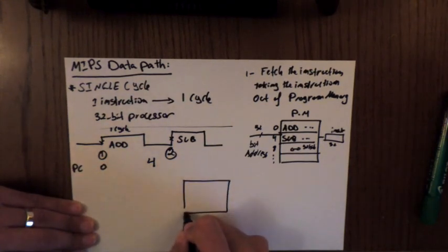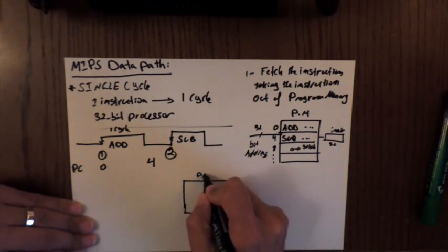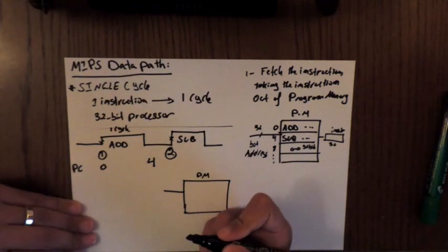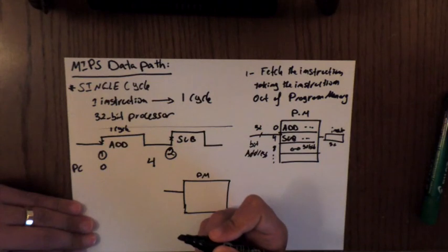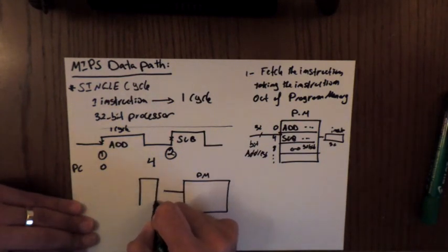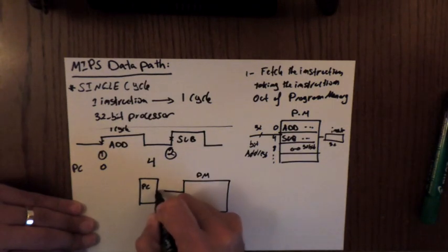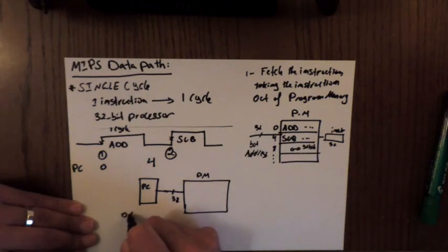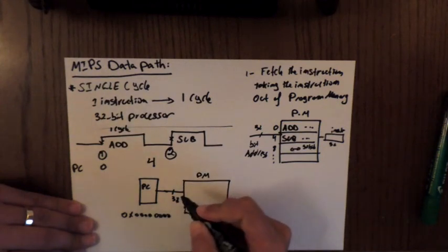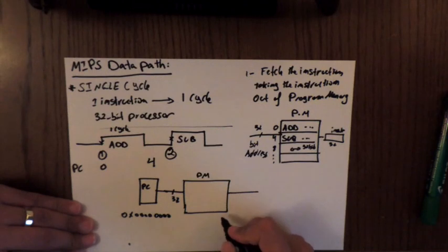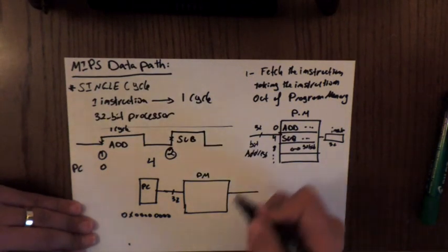So this can be drawn and designed very easily. So this is the program memory, as we said, and the PC is just a 32-bit register. So we have something like this. So this is the PC. This is the 32 bits. So here we start with 0x. So this is the first. And now after the execution of the first instruction, we need to add 4 to it.